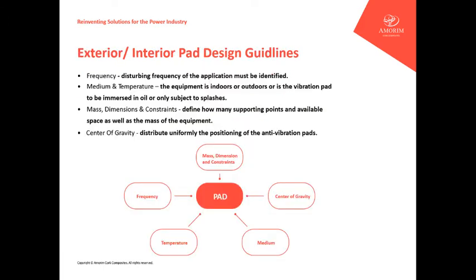Looking a little deeper on the vibration pad solution, we need to design the correct solution or the ideal solution. We need to have all these factors in account, namely the frequency. We need to know what's the frequency of the transformer, which in the case of transformers we know will be 100 Hertz or above.